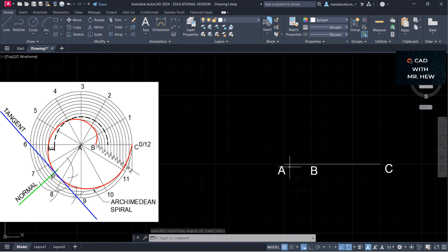All right, now the next thing we're gonna do, we're gonna draw lines radiating out from A going right around. So the first one would be at 0 degrees. So we're gonna go line from A. The length of the line will be 70, and the angle would be 30.